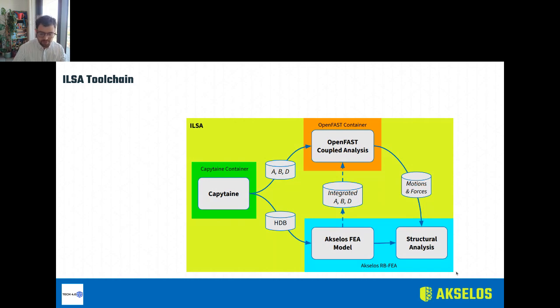This makes it possible to accurately, robustly take all the loads from the coupled analysis and map these onto our FEA model. That includes inertial loads, acceleration, force loads, tower-based force, mooring line forces, as well as hydrostatics, radiation, diffraction, and Morison loads.